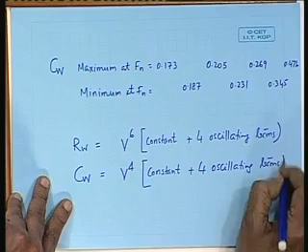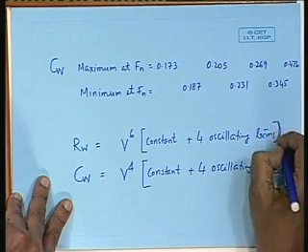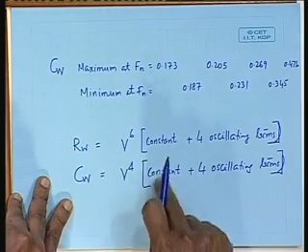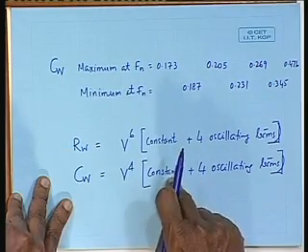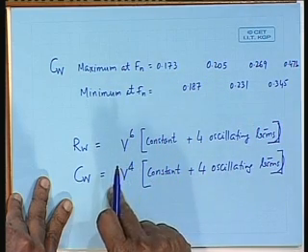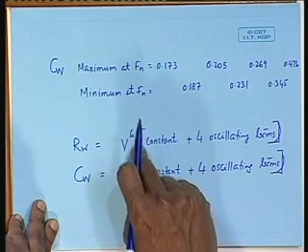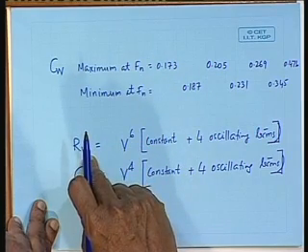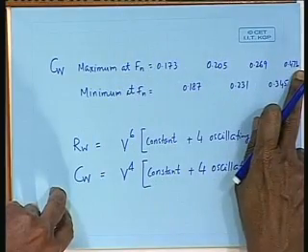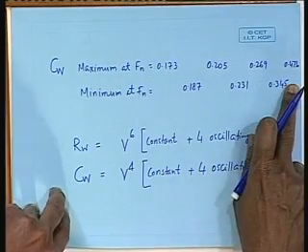So, you see what is going to be the nature of the wave resistance curve. This will increase with speed, this part, at the rate of the 4th power of speed for Cw and the 6th power of speed for Rw, and there will be 4 oscillating terms which may coincide to give a hump in the wave resistance curve or a hollow in the wave resistance curve. Hump means there is a rise in the curve which is represented by these Froude numbers, and a hollow in the curve which is represented by these Froude numbers.